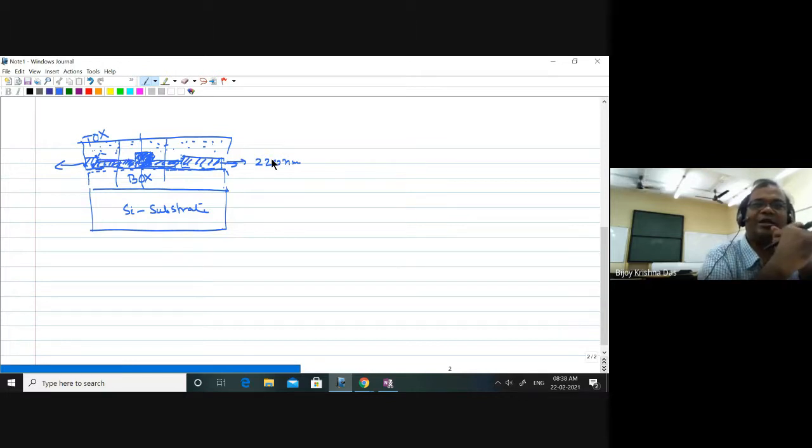But here, if the electromagnetic wave is in a material medium that is transparent, you can ensure that there is probably no heating loss. So energy will not be lost due to heat generation. That is for sure. But one more thing to keep in mind: if the surface is not smooth enough, then you can encounter scattering loss. So the loss of the waveguide will increase if the surface is not smooth.